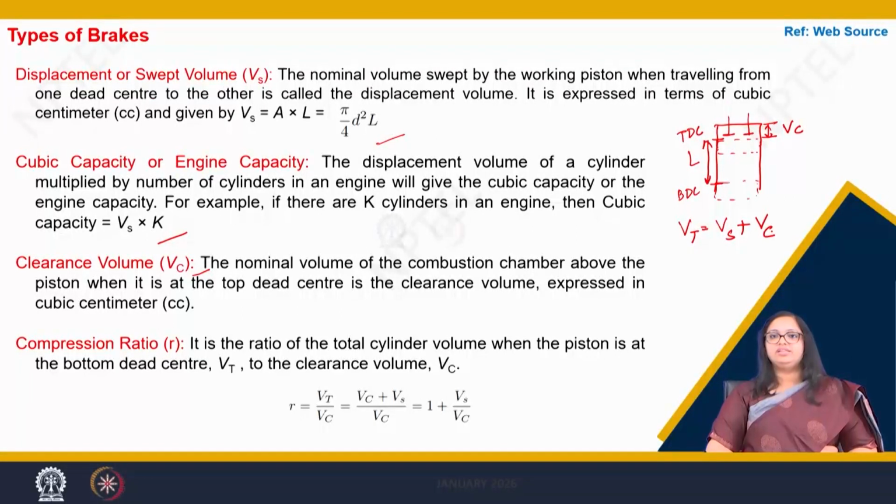So, if my cylinder has a certain volume, how do I find the clearance volume? It is total volume minus the swept volume. So, that small area that lies on the top of the cylinder, after my piston reaches the topmost point, it can reach inside the cylinder. The volume that is remaining above the piston, we call a clearance volume.